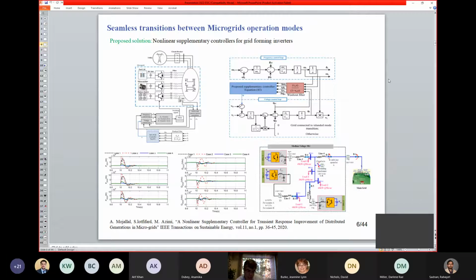So the issue there is that you have a sudden change in the strength of the system. You have a small islanded network with a significant reduction in the strength of the system in a short period of time, and also a switching between modes of the inverters. You can easily observe in some of our simulation cases and reported real-world cases that you have some unintentional oscillation in the system that may cause you to not be able to successfully transition to the post-fault condition.